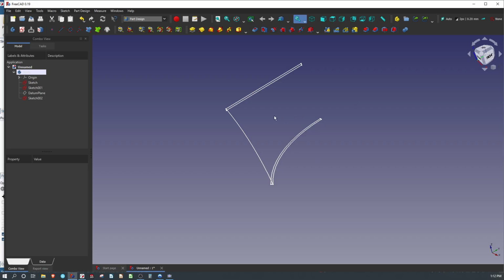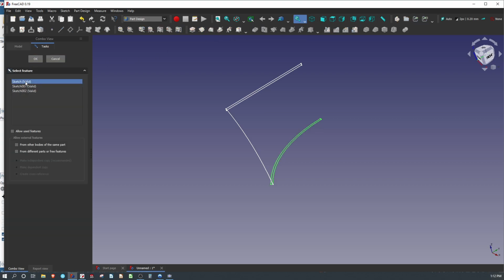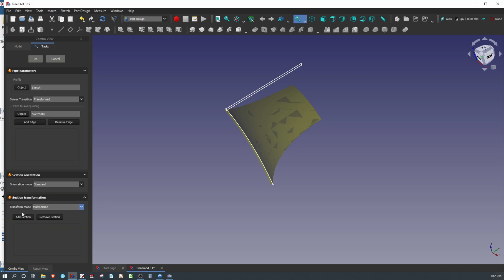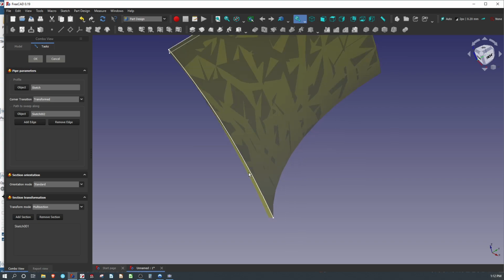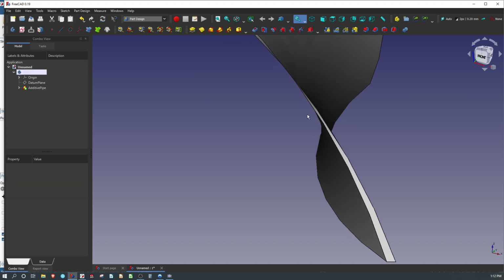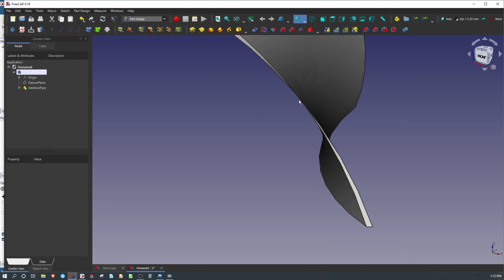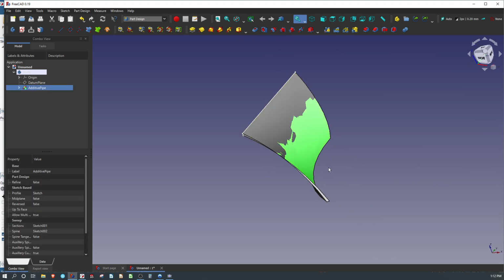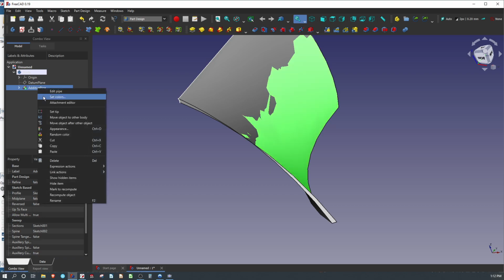So I'm going to go back to FreeCAD. Let's do the same thing. In FreeCAD, this would be a sweep. I'll choose my sketch, and then I'll choose my path to sweep along. And then we want a multi-section transform. And I'm going to add my final sketch. And it looks like I've got a little problem here. My inside surface is intersecting. I'm sad about that.